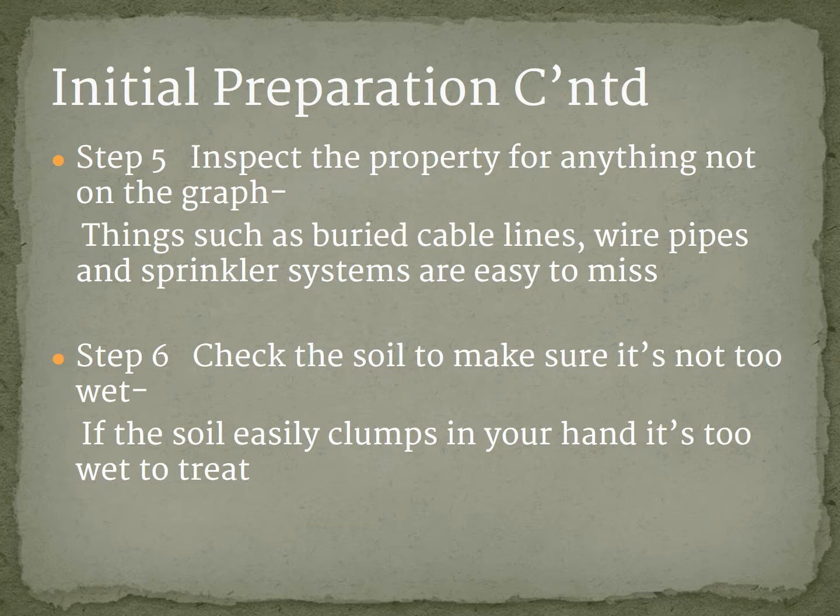I can tell you, I've had problems with pretty much all these, especially the buried cable lines. I can't tell you how many times I've hit buried cable lines or sprinkler systems right up against the house, and you would think, well, I can just trench because surely somebody wouldn't have them within 12 to 18 inches of the house. Unfortunately, a lot of people will do their own work, and they'll set things up that are not necessarily by protocol, and also they won't use conduit. So when you go trenching with a pickaxe or even a shovel and you're digging in this dirt, it's real easy to sever these lines.